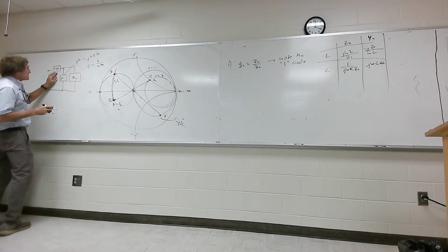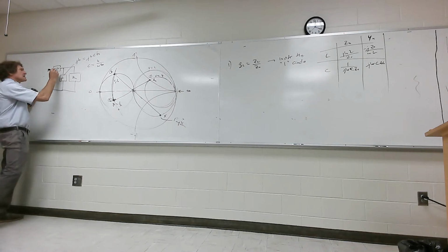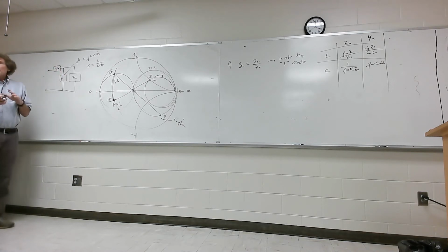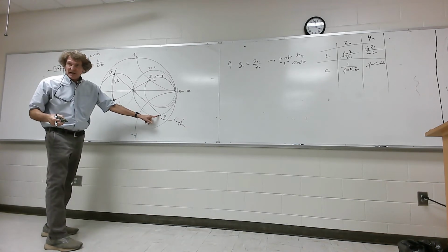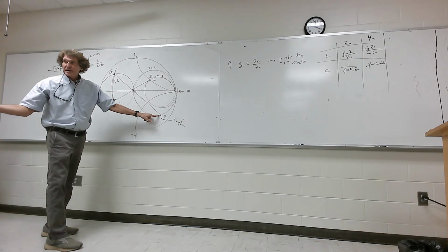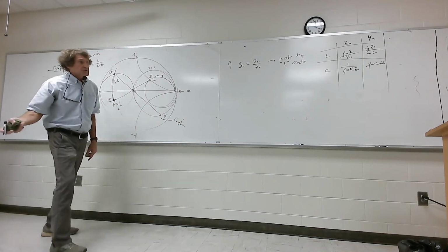So then for this one, that's normalized impedance, right? And if I wanted a positive value, like if you're down here, if you have minus JX, then you want to add a positive JX, which would be what? An inductor, right? So it would be this right here.